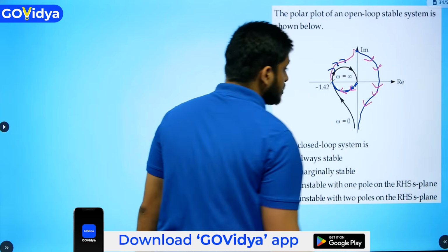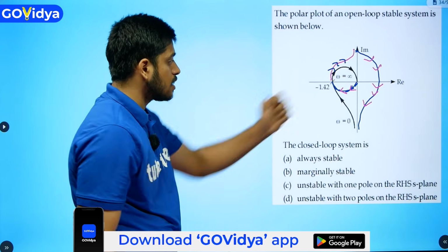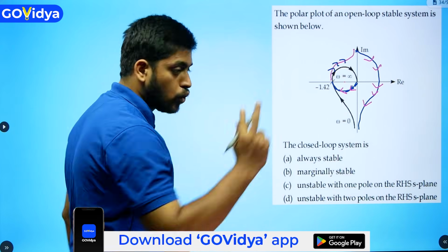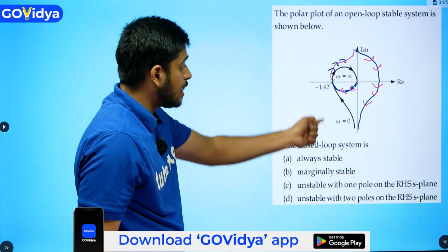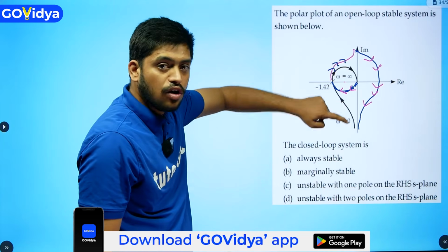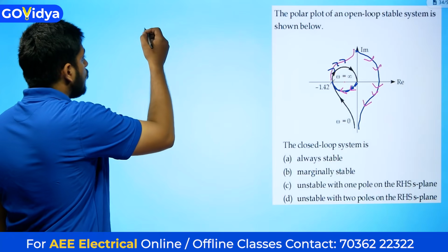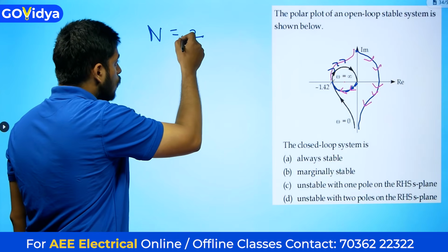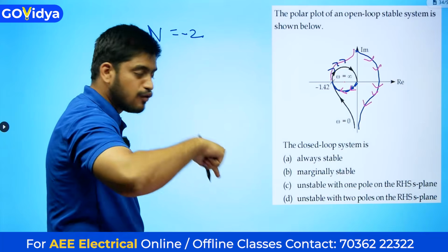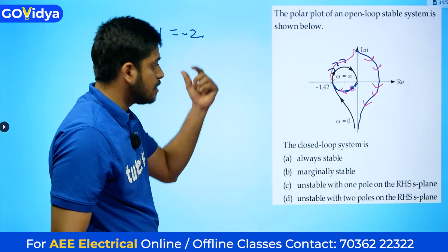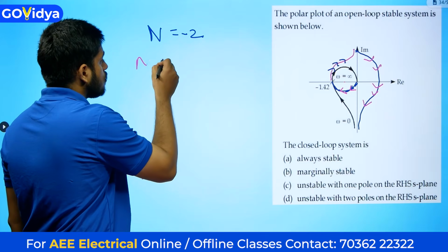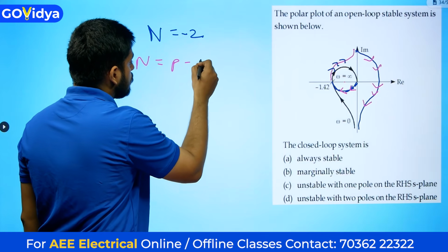So for the number of encirclements, -1 is going to exist somewhere here. So -1, 0 would be 2. So 2 in clockwise direction only, both are clockwise, not anti-clockwise. So we have N equals 2 here, but as it is clockwise, we are going to get minus. If it would be anti-clockwise, the sign would be +2 only. And next, what is the value we have? The equation N equals P minus Z.